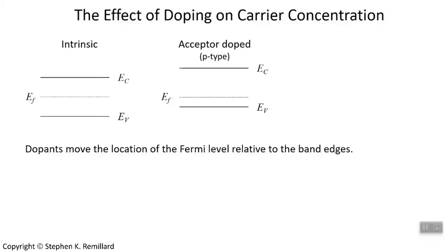If you add impurities that contribute electrons, the opposite happens. The Fermi energy gets pulled near the conduction band edge. So those two types are then referred to as either acceptor doped or p-type if you create holes, or donor doped or n-type if you create electrons. Those terms will be used interchangeably. Acceptor doped and p-type are used interchangeably.